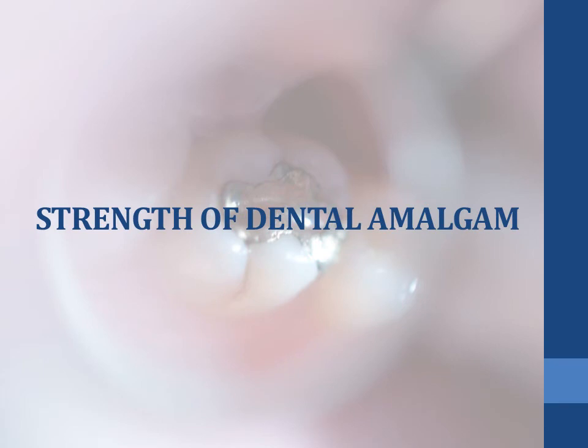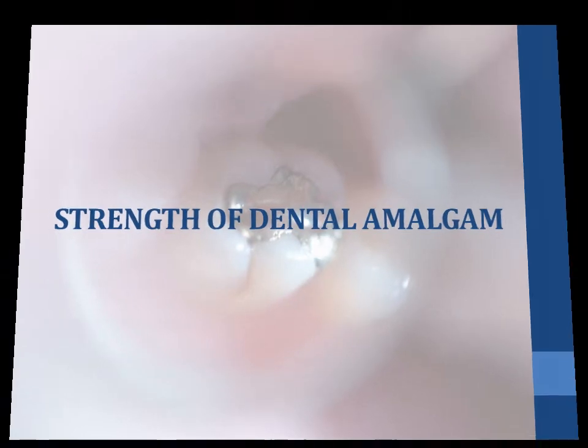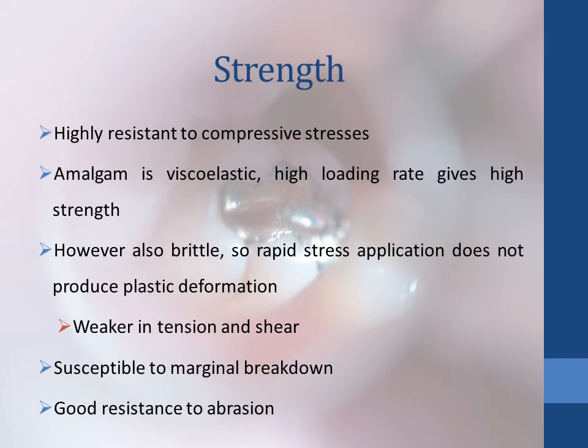Now let's move on to the mechanical properties of dental amalgam. Now the strength of dental amalgam: it is highly resistant to compressive stresses. It is viscoelastic. High loading rate gives high strength. However, a drawback is that it is brittle, so it is weaker in tension and shear. And rapid stress application does not produce plastic deformation.